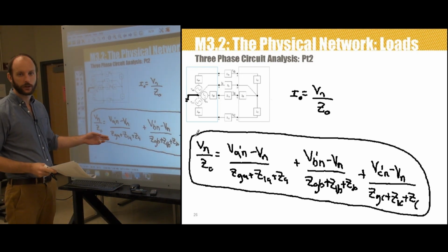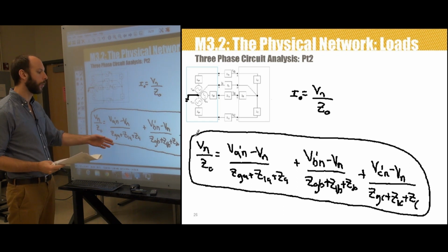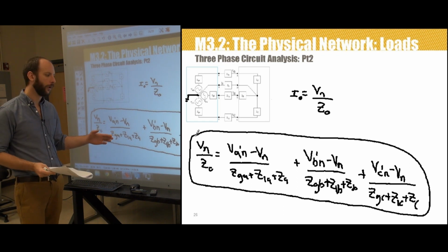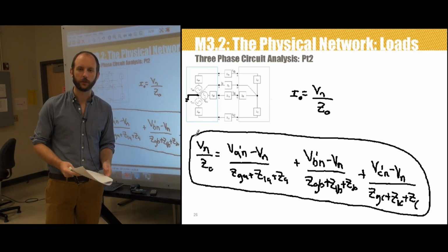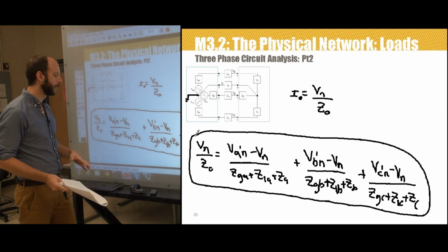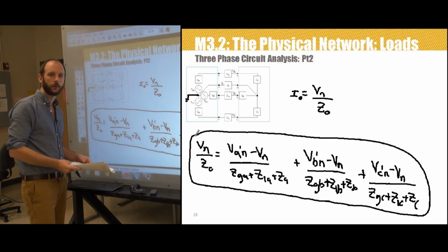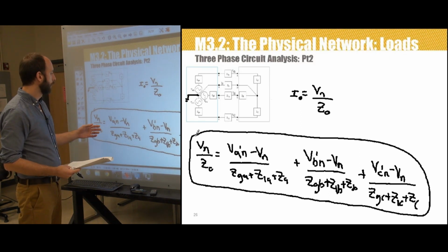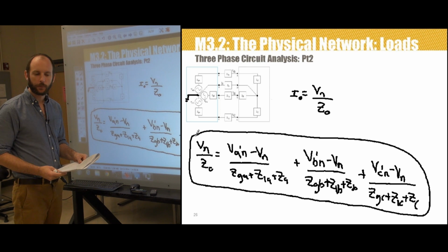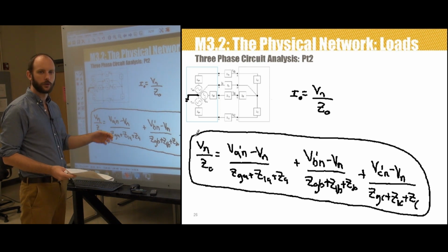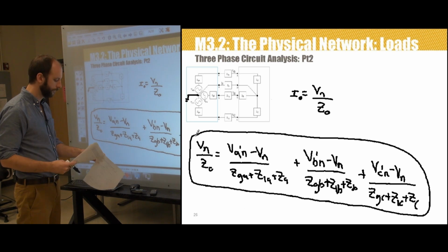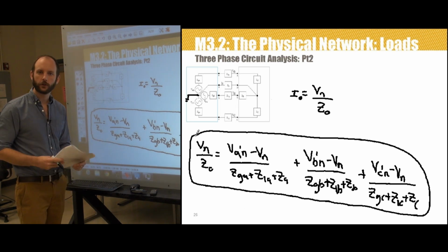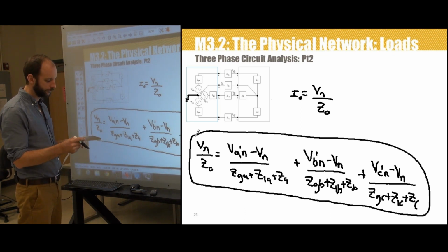So this gives us really the general circuit equation for any YY configuration. It's not required that it's actually a balanced load. Most typically we will analyze balanced loads, but because we've included the impedances individually, this is the equation that we would need to solve for any system, whether it's balanced or unbalanced. So this is kind of the mothership here. So write that one down in your notebooks and highlight it.